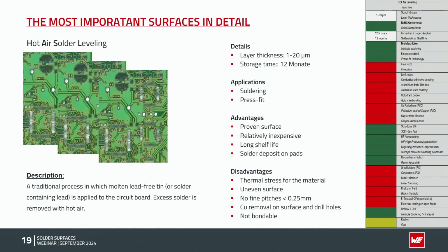There's also some copper dissolving in this process, so we have to start with more copper in the through-hole platings if you want to do a hot air solder leveling process. So this is an additional cost aspect adding to the costs for this solder surface. And finally, it's not bondable.